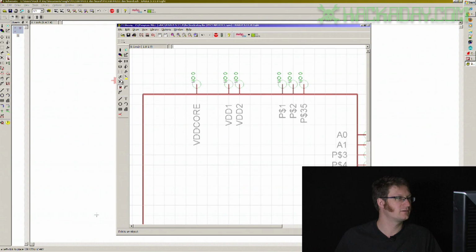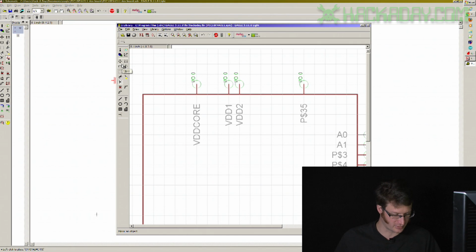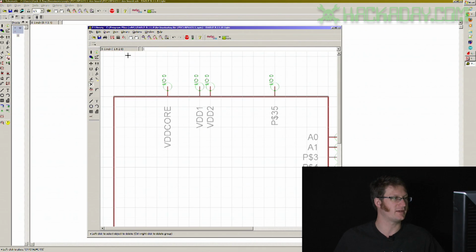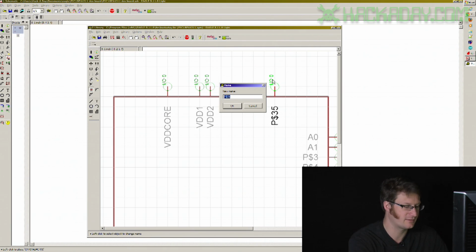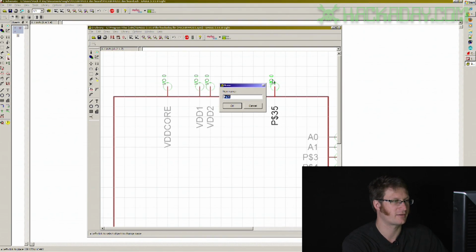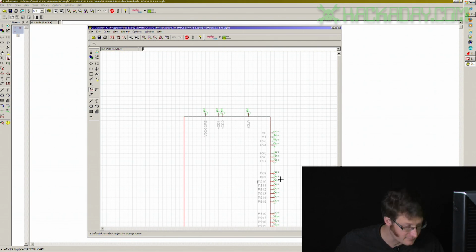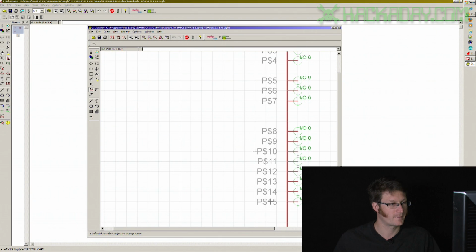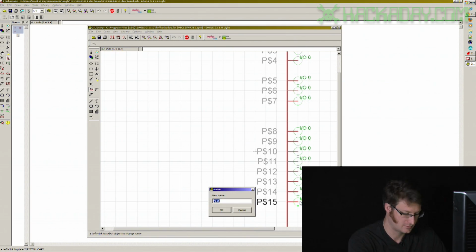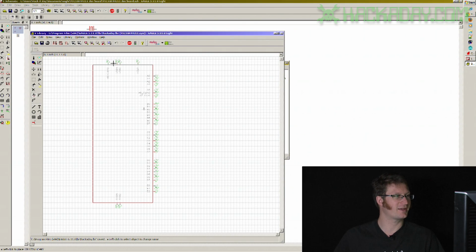We're only adding one extra pin up here, and that is the memory clear pin, which is used in in-circuit serial programming and as well to reset the device using a button or something like that. The other pins that you use to do in-circuit serial programming are actually on port B. So they are on port B 6 and 7. So I'll relabel this one. Alright, now I have labeled all of the pins.